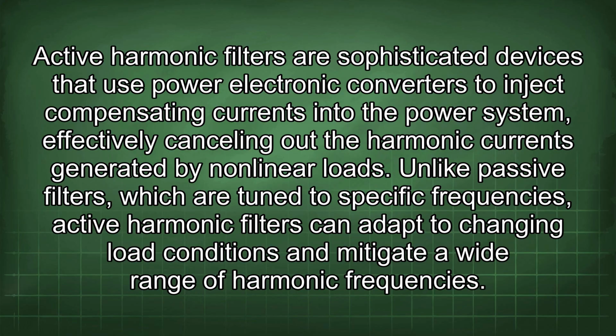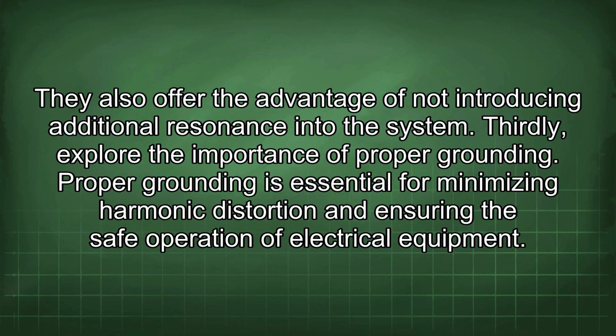Unlike passive filters, which are tuned to specific frequencies, active harmonic filters can adapt to changing load conditions and mitigate a wide range of harmonic frequencies. They also offer the advantage of not introducing additional resonance into the system. Thirdly, explore the importance of proper grounding.